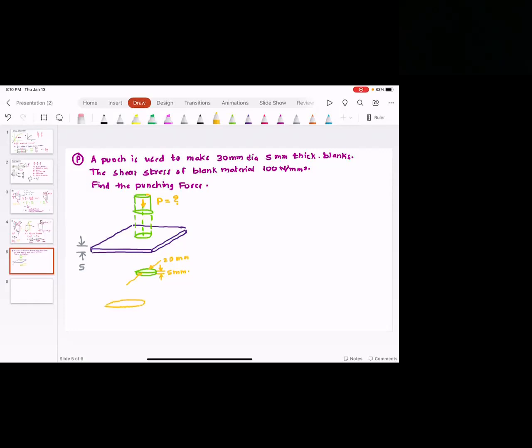So if you think about, let me draw you. This failure, remember this word, is called circumferential shear. And we will study this in design of cotter joints. We'll study this in design of knuckle joints. So this failure is circumferential shear. And circumferential shear is, if you were to cut that strip open and stretch the strip.